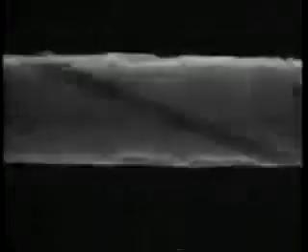This is an oscilloscope display of a radio frequency carrier, amplitude modulated by my voice, using conventional AM techniques. Now, by conventional AM, we mean double sideband, unsuppressed carrier amplitude modulation. The important thing to notice here is that when the modulation is removed, the radio frequency carrier remains.